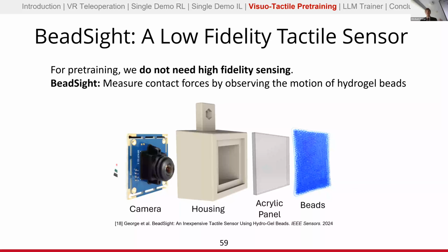That being said, it's much tougher than any kind of silicone-based method because we have this very rigid case over it. And because the beads move, that means we don't have those shear forces being applied to it. So for the cable plugging test, it was useful because once again, we had a not so well trained robot occasionally trying to plug in the USB cord, so you ran into these really high forces. Therefore, this inexpensive, much more physically robust sensor worked well for this case, but specifically just for pre-training, because that sensor itself is not that great.